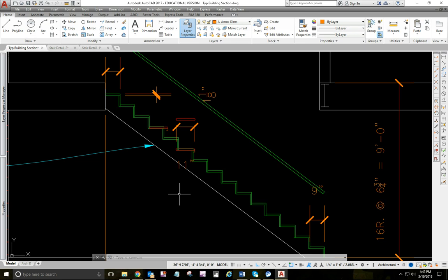Now, if you go into an unfinished basement, you can have a steeper stair, which would have a more narrow tread. If your stairs are going up into an attic, an unfinished space, you can have a steeper stair, which has a taller riser and shorter tread.